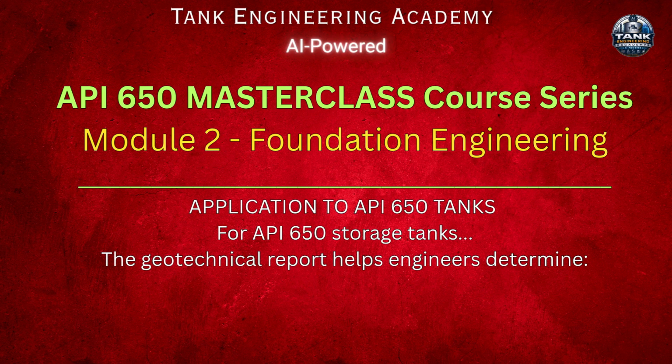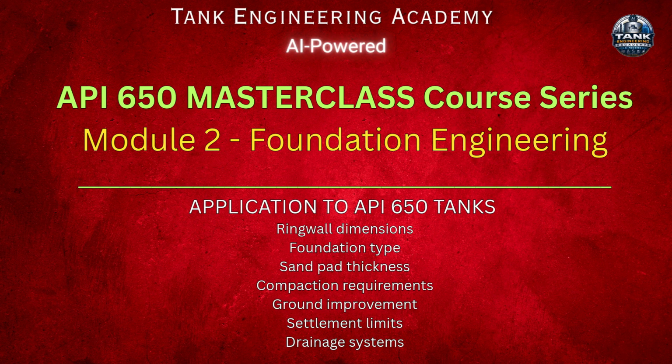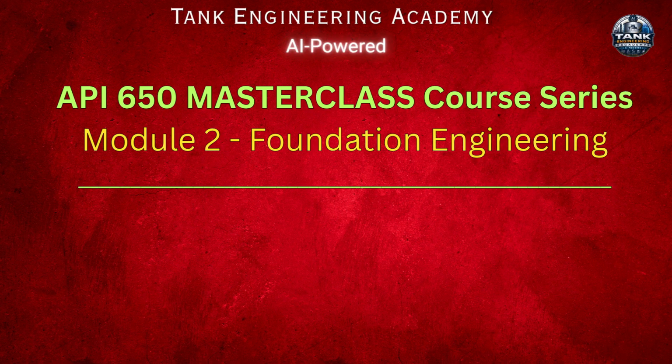Application to API 650 tanks. For API 650 storage tanks, the geotechnical report helps engineers determine ring wall dimensions, foundation type, sand pad thickness, compaction requirements, ground improvement, settlement limits, drainage systems. Without accurate soil data, safe tank design is impossible.